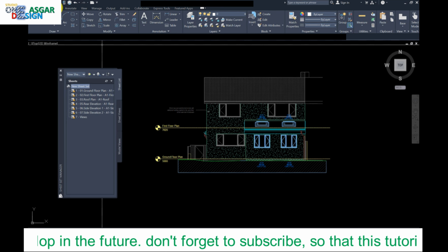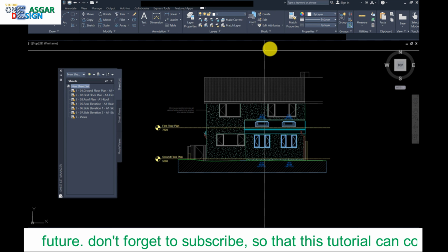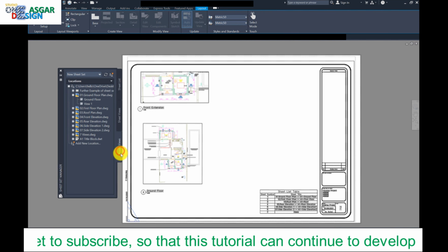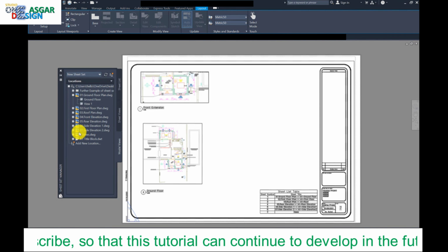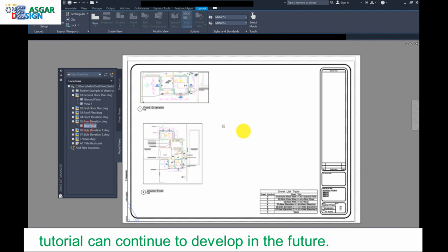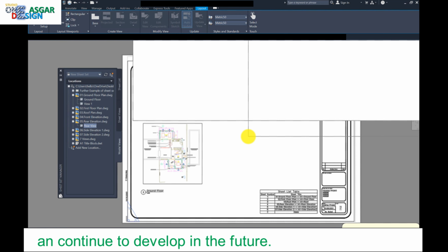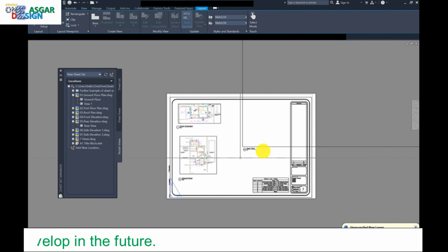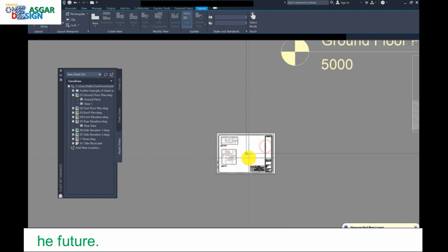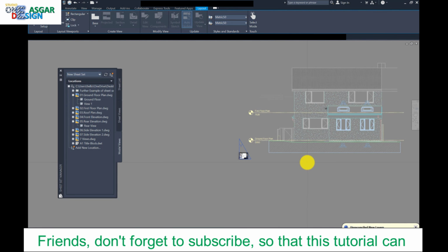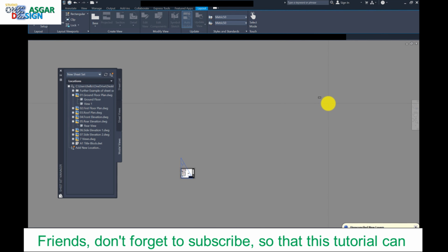So in our rear elevation plan, we'll then save it. Move on back to our views plan. We'll now move on to our model views. Go to our rear elevation. Click and drag it onto our sheet. And click to place. So again, we'll select it. Go to our scale and change it to 1:100. Move it into the drawing.